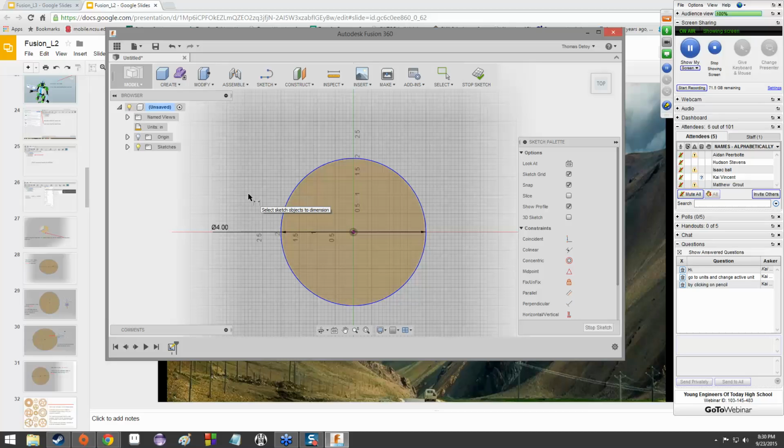So there's this thing, right? It exists. Pretty sure I could have made that more vague. Anyway, it's called the construction line. Construction lines are things which are a part of your drawing, which help you get a scale of things or keep track of certain aspects of your drawing, that you can add anywhere, that are a part of your drawing but are not a part of the physical object.